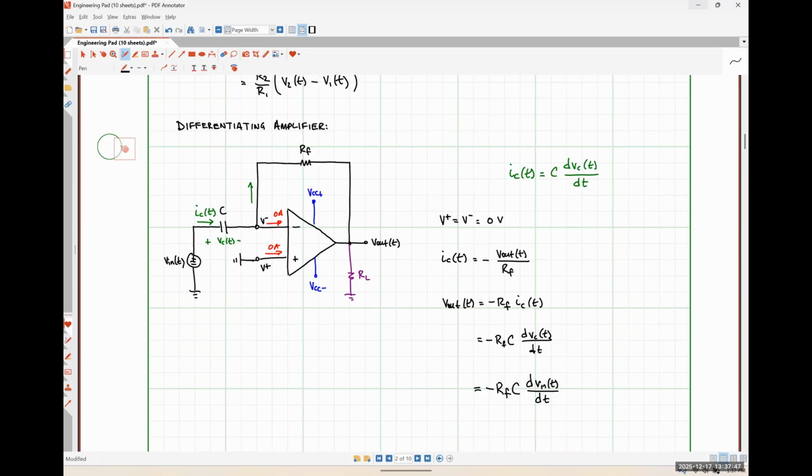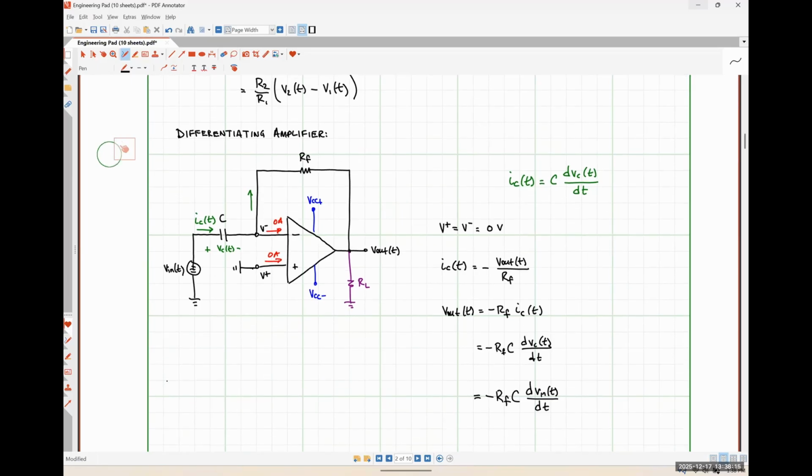And the reason why they should do the opposite mathematical operation when you just switch them out is because they have the opposite relationship, right? So the IV relationship, the derivative-based relationship for the capacitor is going to be the same thing as the integral-based relationship for the inductor. So yeah. You typically only see capacitor integrating? Correct. For the exact same reason. You just don't really use inductors to do integrating or differentiating amplifiers in practical circuits because, like I said, there's a lot of tolerance issues.